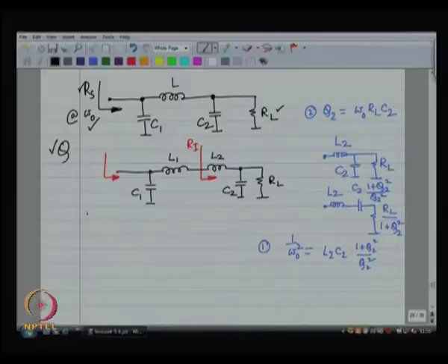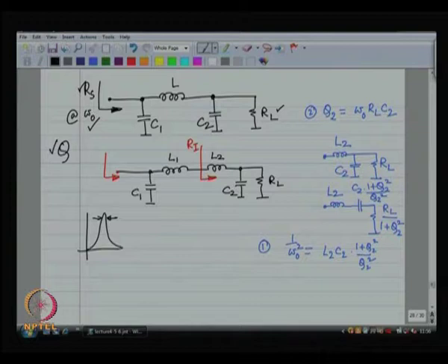So, the net characteristics is going to look like this. So, I want a definition of this. So, that is my bandwidth, that is the bandwidth of the matching circuit. It matches over that band approximately. It matches perfectly at only one point, but approximately over a range of frequencies. Okay, so, that is my overall Q. Okay. So, what is this quantity? If I have a circuit which has C 1, C 2 and L, what is the overall bandwidth of the match?